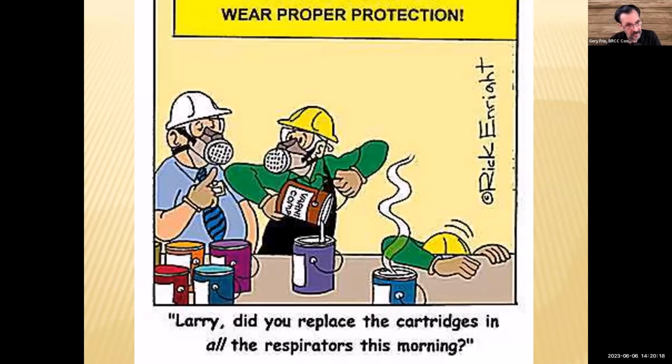Cleaning them is problematic. From a distance, you could blow dust off of stuff or wipe dust off of them with a rag. But taking an air compressor and blowing through them, you can punch holes through the filter. And that's the same as not having a filter at all once you've got holes in them. This happens with people with cars sometimes. When they're doing maintenance, they'll blow the dust off of their air filter for the engine and end up ruining the engine, because you're letting dust particles into the engine that are getting past the filter because you punched holes in it. They're maybe not something you can see, but big enough for particles of dust to get in.